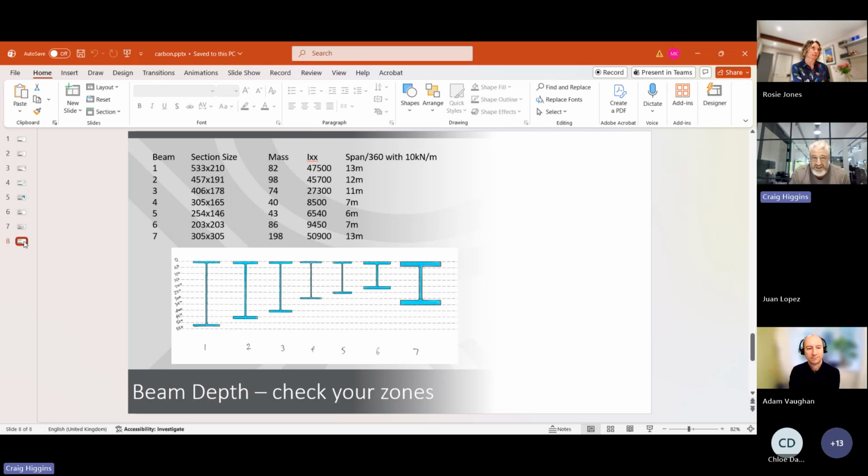doesn't impact the ceilings, doesn't impact the building services. And this sketch really is showing you another thing, which is what Rosie was saying, integrating services and structure into a building early doors, and saying, well, actually, do I have an appropriate floor-to-floor height? Because if someone's set a floor-to-floor height and put in a planning application and gained planning for a building before they've got a services strategy, before they've got a structural strategy, then the reality is your building will probably have already failed from an embodied carbon point of view, because, as Rosie pointed out, between 50 to 60% of that embodied carbon is going to be structure.